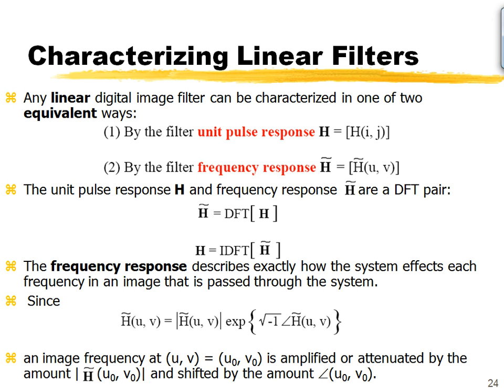Fourier domain, right? It would be easier for us to look at the Fourier domain and say, okay, now it's very easy for me to come up with a filter for that particular domain. Of course, if I wish to apply that filter, I may not wish to actually do that application in the Fourier domain. So what you would do is design the filter in the Fourier domain, take its inverse Fourier transform, inverse DFT, and then say, okay, this is my space domain filter. And I would convolve that with my image using linear convolution. Okay? And the resultant I would get would be my filtered image.